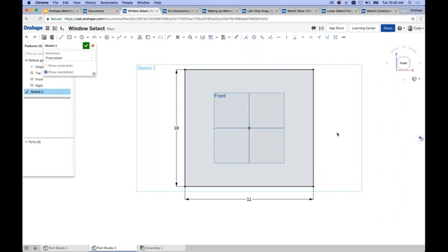Right? Move to this line, same thing. Now, what you may run into from time to time is occasionally it's difficult to select these flags. In this case, it's a very simple sketch, and that's not the case. I can easily click the flag and hit delete and delete that constraint. But what if I'm struggling? Let's say, for instance, I mouse over my geometry, and then I move my cursor and that flag just disappears, and I can't select it and easily delete it.